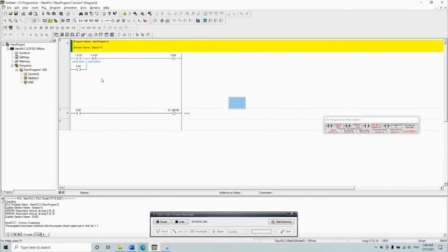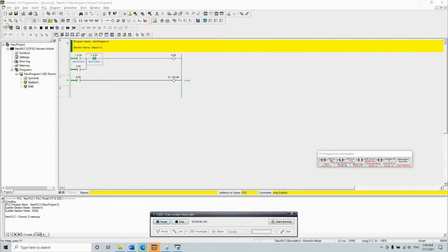And after that, you have to select the PLC and work online. It will display this, and you just simply click yes. After that, you can see the green line on the ladder diagram shows the PLC is in online mode.